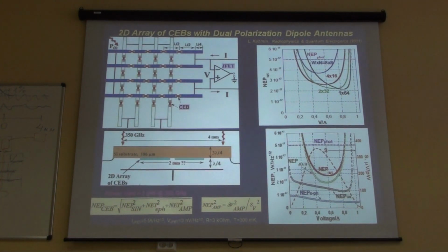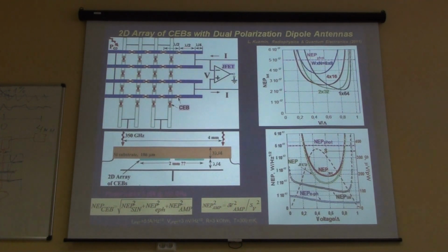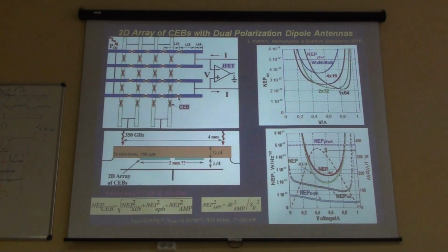But anyway, how do you make the bridges? I mean, the crossings. Usually there are two ways. One is insulation made exactly by aluminum. Simply we open the chamber and the aluminum is oxidized, and it's really enough for oxidation. But then we sometimes find problems. We are not sure exactly with this one. We also put an additional layer of silicon monoxide or silicon dioxide. In this case, it's twice as reliable.